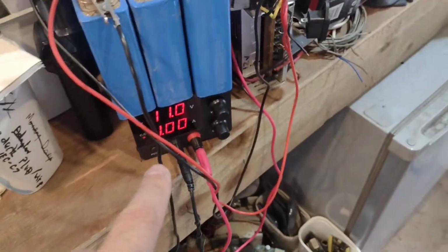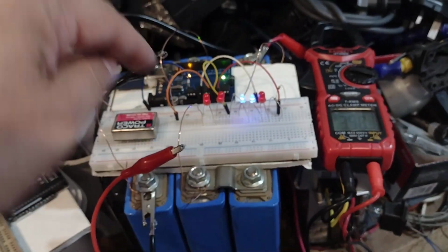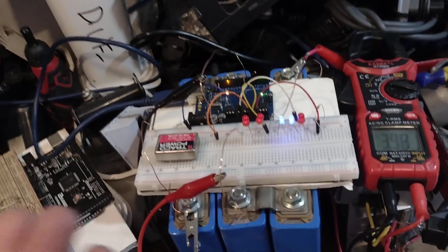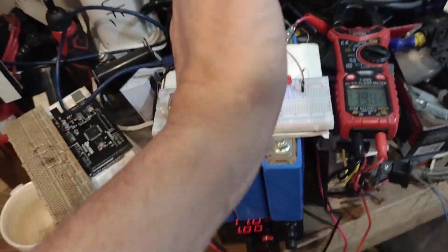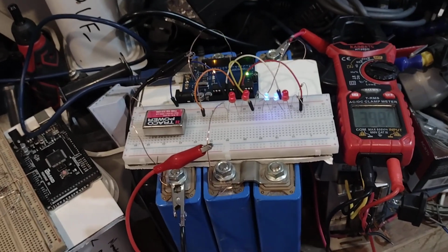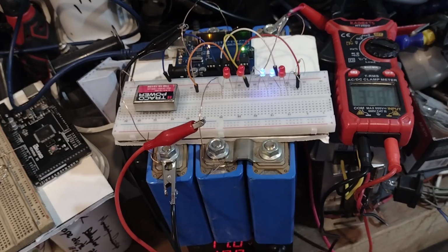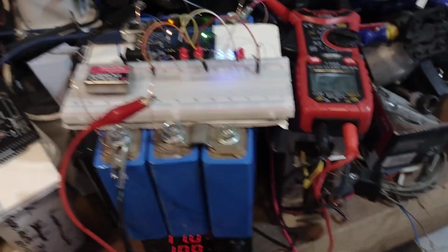Essentially what I'm trying to get at is, when this is hitting 12 volts, potentially this cell in the middle, it's not the right calculation, but in essence it's supposed to be at 4 volts when fully charged. So potentially we could have this one in the middle at 4.7, which is going to fry it. That's the problem that you've got.